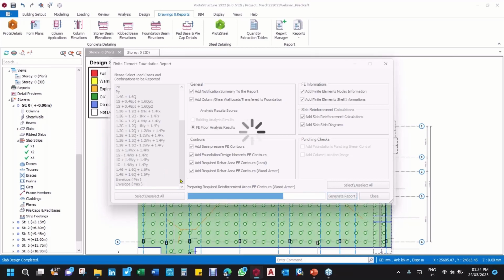And while we are waiting, like I told you before, if there are failed piles, you can either increase the pile capacity or increase the number of piles, or even both. You can also increase the thickness of the raft, but all this will also have their own effects.